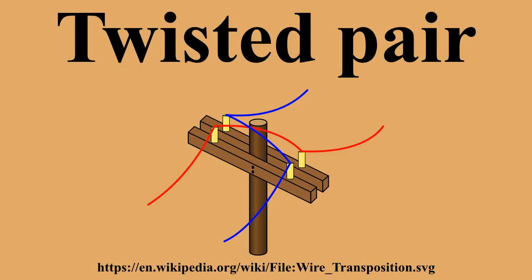Unshielded twisted pair. UTP cables are found in many Ethernet networks and telephone systems. For indoor telephone applications, UTP is often grouped into sets of 25 pairs according to a standard 25-pair color code originally developed by AT&T Corporation. A typical subset of these colors shows up in most UTP cables. The cables are typically made with copper wires measured at 22 or 24 American wire gauge, with the colored insulation typically made from an insulator such as polyethylene or FEP and the total package covered in a polyethylene jacket.